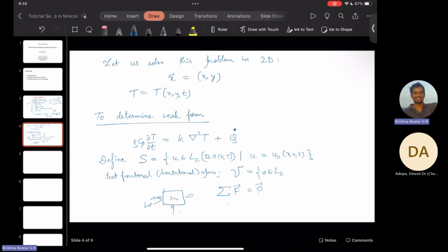Now, if we multiply all forces by a certain virtual displacement, virtual displacement means we are just applying it on the body theoretically. We are not actually applying it, because we can never have that the work will be zero, right? So we multiply with certain virtual displacements such that the work is still zero. Because if on both sides you multiply with delta r, zero multiplied by delta r is still zero, right? So this is what we call the virtual work principle.